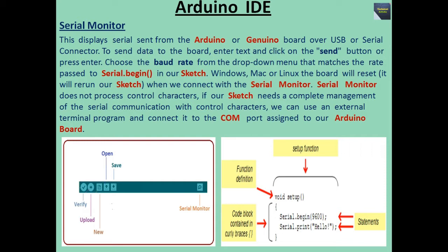Serial.begin, and within parentheses if you write 9600, which is passed as an argument, it passes the value 9600 to the speed parameter. This tells the Arduino to get ready to exchange messages with the serial monitor at a data rate of 9600 bits per second, that is 9600 binary ones or zeros per second, and is commonly called a baud rate.